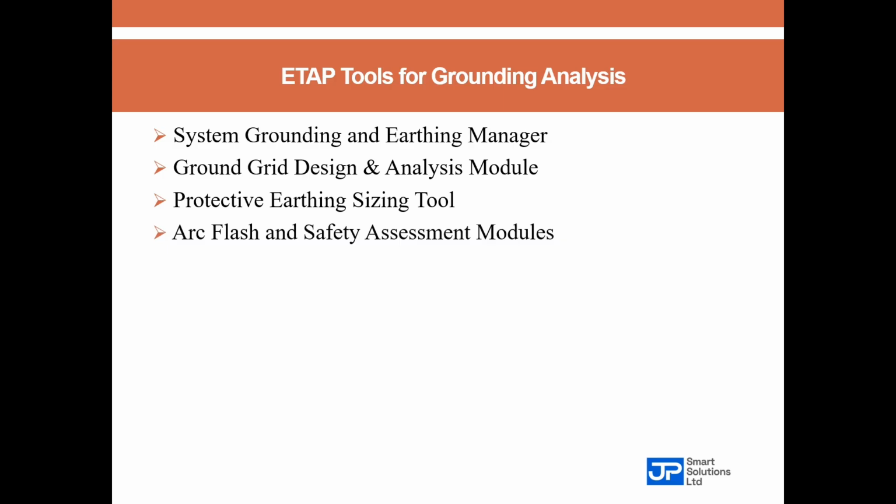And finally, we have the arc flash and safety assessment model. Now, all these other settings integrate directly to the ETAP arc flash and safety assessment models because we are going to be using this as a point of reference. As I said earlier, it affects the incident energy. So it will affect your arc flash results, your arc flash labels. So if your grounding data is wrong, your entire arc flash energy calculation could be wrong. These tools are there on ETAP software, but then many engineers never even open them.